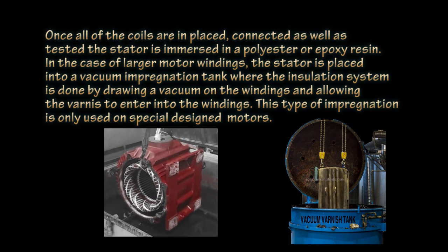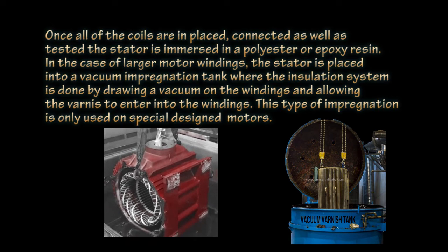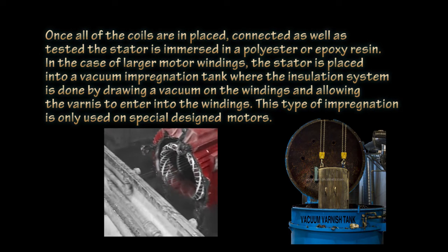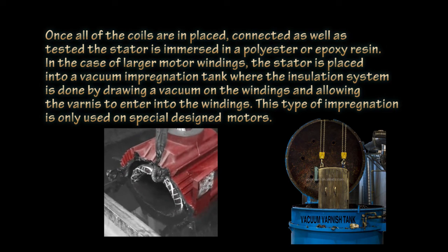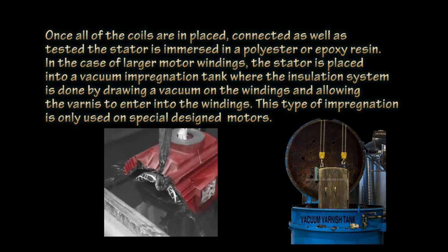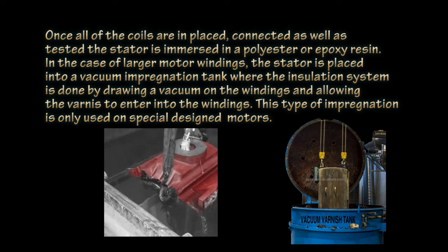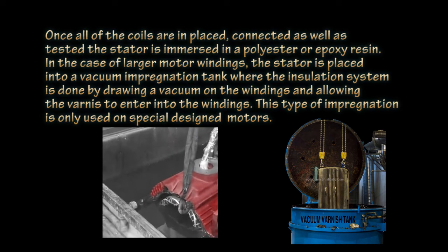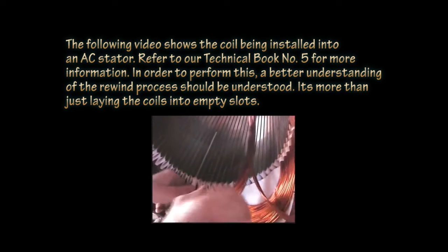Once all of the coils are in place, connected as well as tested, the stator is immersed in a polyester or epoxy resin. In the case of larger motor windings, the stator is placed into a vacuum impregnation tank, where the insulation system is done by drawing a vacuum on the windings and allowing the varnish to enter into the windings. This type of impregnation is only used on specially designed motors. The following video shows the coil being installed into an AC stator.